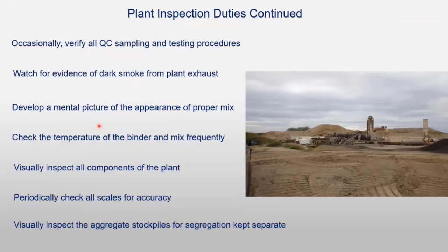So some other duties, and more of a visual thing, is occasionally you want to go into the QC lab and watch them do some tests, and watch for evidence of blue or dark smoke. That means the mix is getting too hot and starting to burn off some of the binder, damaging the binder some.